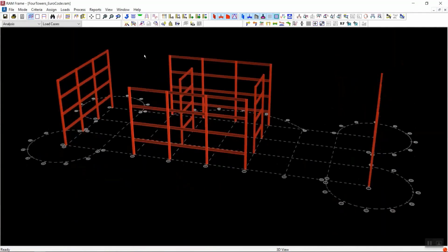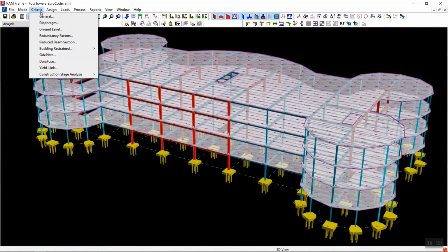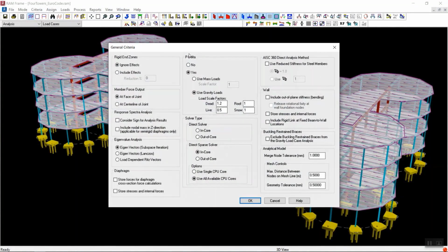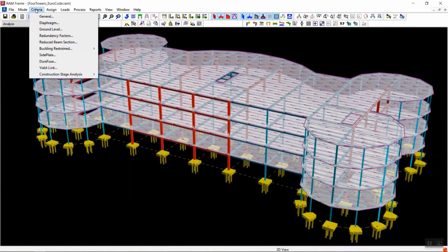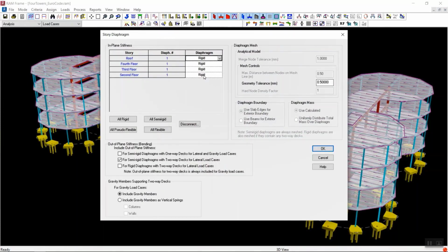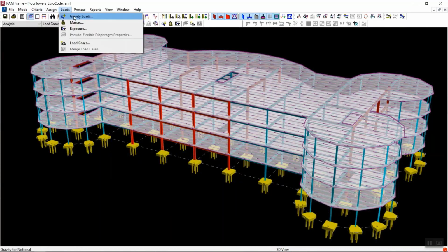It is this part of our structure that needs to be designed stronger, because they are the ones which are going to resist our lateral load. So these are the criteria. I'm using the P-delta analysis for this building. Singapore National Annex says that you need to do seismic analysis only if the building height exceeds 20 meters. This building is not exceeding 20 meters, but just for demo purposes, I still employ the seismic analysis for this 4-story building, which is less than 20 meters.